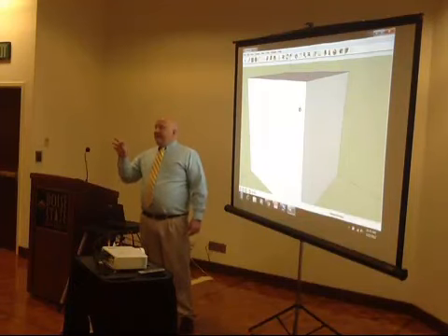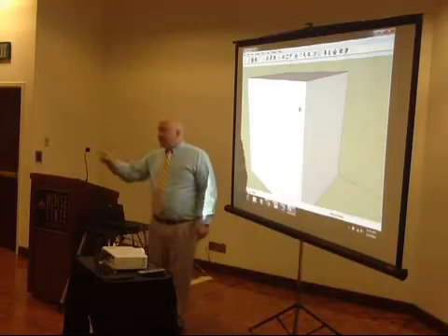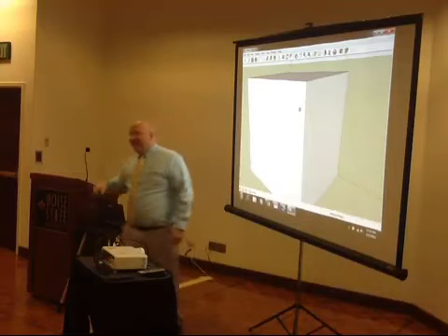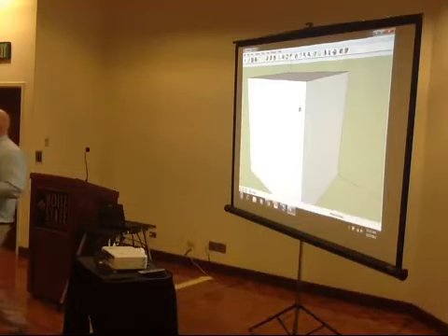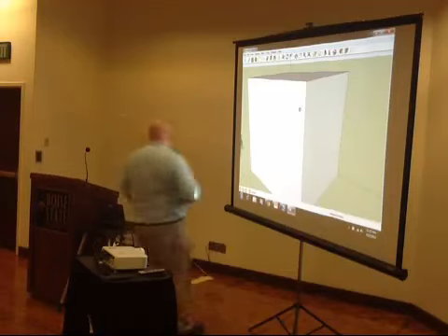You can click and hold the scroll wheel, and I believe it should orbit. Is it orbiting when you click and hold? So that's by far the quickest shortcut to the orbit tool. Click your scroll wheel and move it around. Okay.